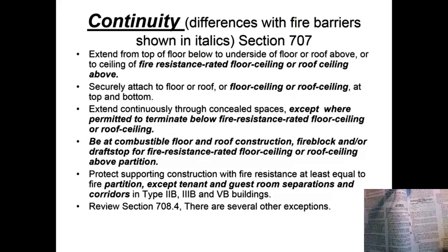So it even talks about here incidental uses. The fire barrier separating incidental uses. We learned last time what incidental uses are from chapter 2. It shall have a fire resistant rating not less than that indicated in table 509.